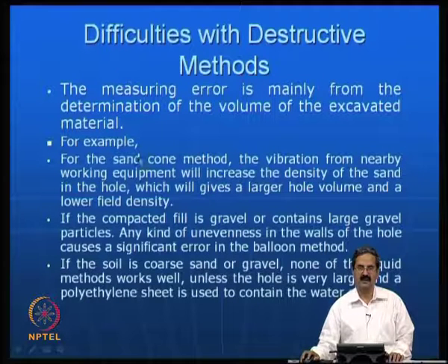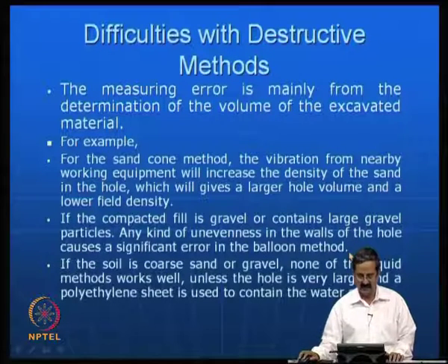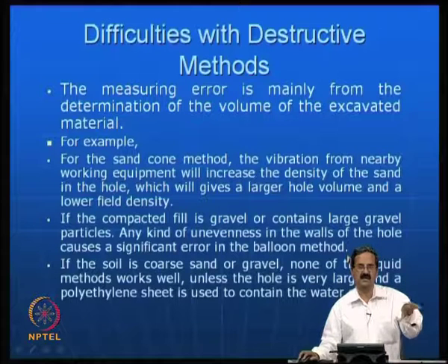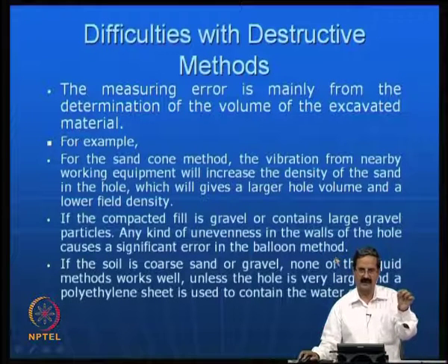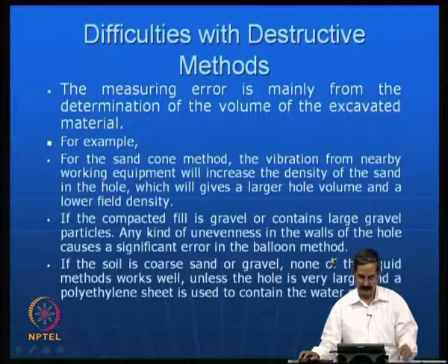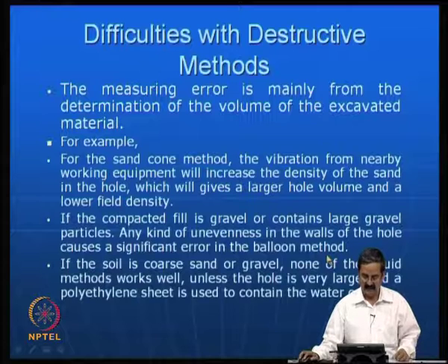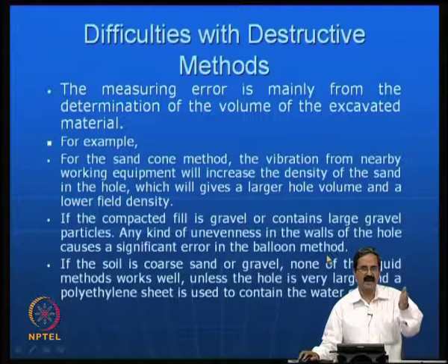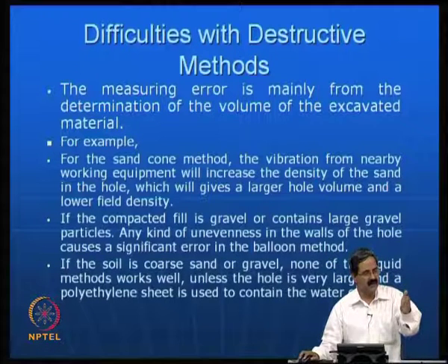Then there are some cases where the compacted fill is gravel or contains large gravel particles. Any kind of unevenness in the walls of the hole causes significant error in the balloon method. Say, for example, in some materials you have a lot of big-size particles. A single lump of clay or a gravel can have a volume of 1 cc, 2 cc or 3 cc. And the surface can be uneven.